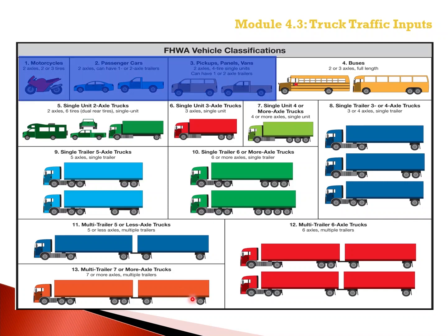The Pavement ME Design software, however, only uses vehicles from Class 4 for buses and through 5, 6, 7, 8, all the way through 13 for the multi-trailer 7 or more axle trucks. So Class 4 through 13 is what is required for the Pavement ME software.